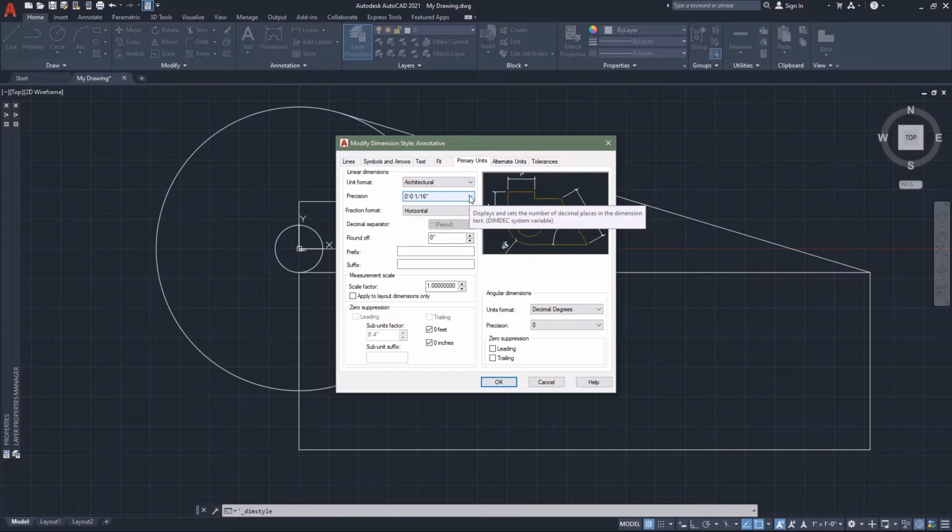We will employ that same philosophy of allowing the software to show the user minute drawing errors and the opportunity to make appropriate corrections here. Left-click on the precision pull-down and scroll down and choose the 1/256 of an inch precision.